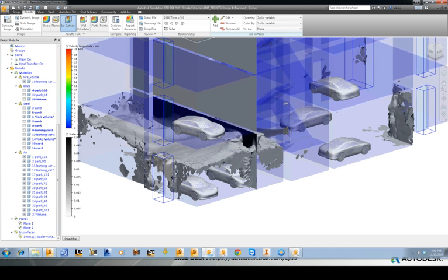Yes, actually, in terms of running humidity models, that has matured over the years. In regards to dew point, we don't really report on that, but sites of possible condensation, we do report on percent liquid that is building up on walls. So if you were to do an atrium design, which we have quite a few customers that do that, and you're trying to design the venting on the floor to control the hot air going up the glass, in other words, yes, we definitely have people that do that fairly successfully. Does that answer that question, Scott?